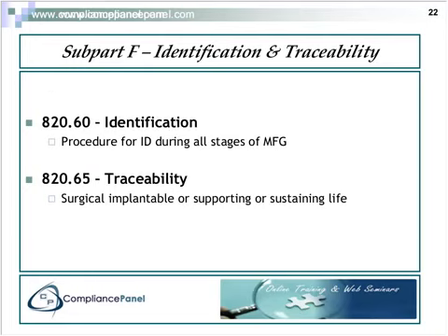Manufacturing personnel. Here you must be able to identify the current manufacturing status for any assembly or subassembly in the production area, and that's where Subpart F comes in, its identification and traceability. So you'll find that this is handled by using material travelers or records and product-specific documentation. But it's very important that you keep these records both accurate and legible.